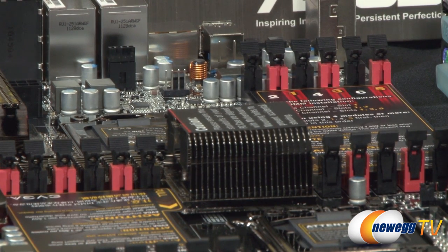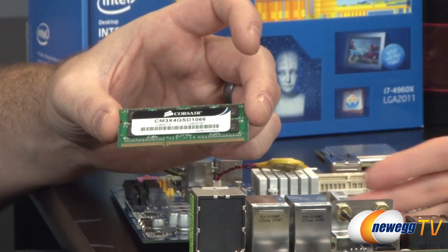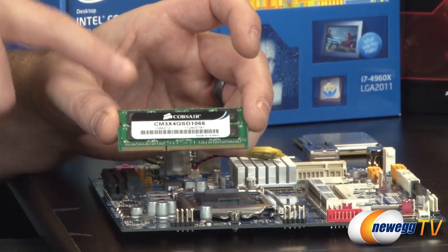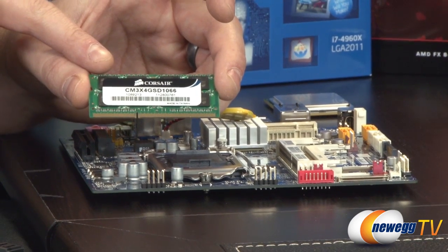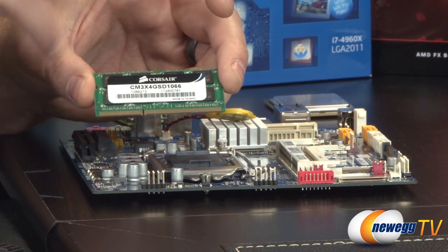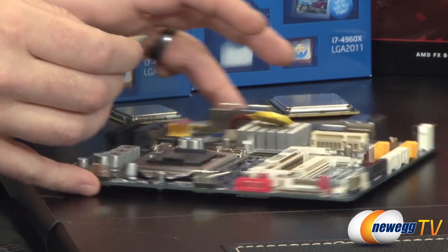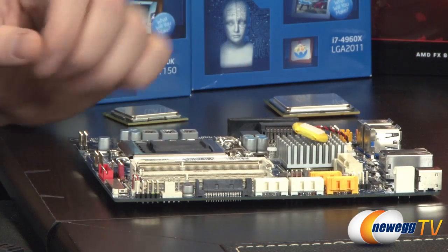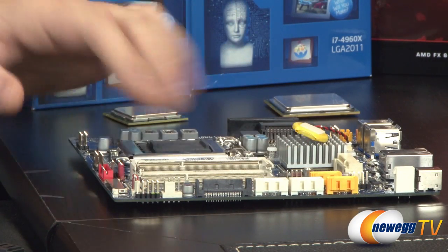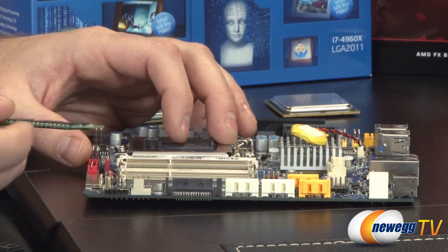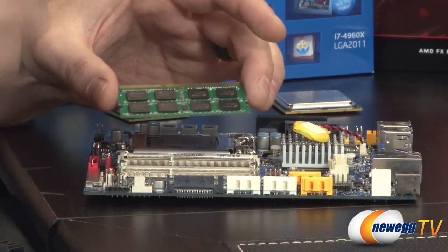And the only other wrench that might be thrown into your memory selection choice, again, this might depend on what motherboard you're using, but occasionally, particularly with these small form factor motherboards, you actually have them using desktop memory. I'm sorry, laptop memory. So this is still DDR3 memory, but this is what is known as an SO DIMM. DDR3 SO DIMMs are designed specifically for use in originally laptops, but you will notice that our little thin mini ITX motherboard here, in order to save space as well as the Z height of the completed motherboard with everything connected, they've gone and used laptop memory. So keep that in mind.